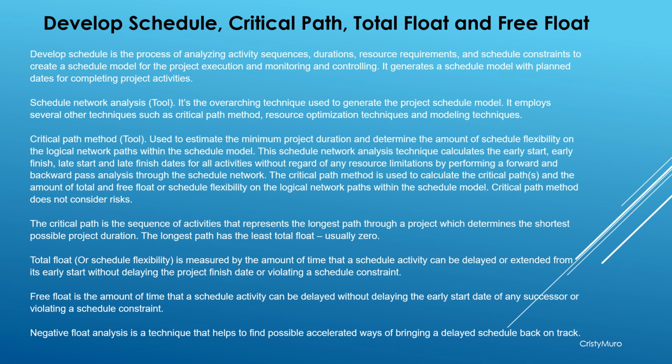The critical path method is used to calculate the critical path and the amount of total and free float, or schedule flexibility, on the logical network paths within the schedule model. The critical path method does not consider risks.